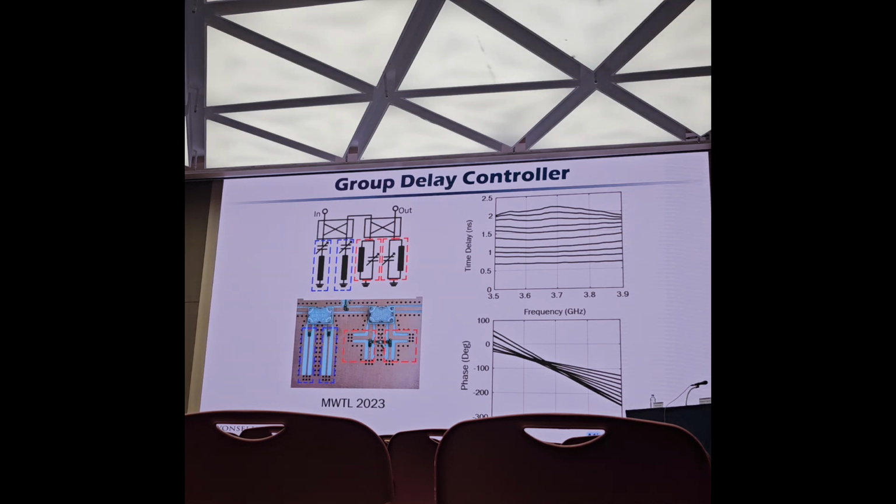Any suggestions to enhance the linearity or the group delay, suppose some application needs a slightly wider band of response? Actually, there is a trade-off between group delay bandwidth and dynamic range. So if we reduce this dynamic range, then we can widen this bandwidth.